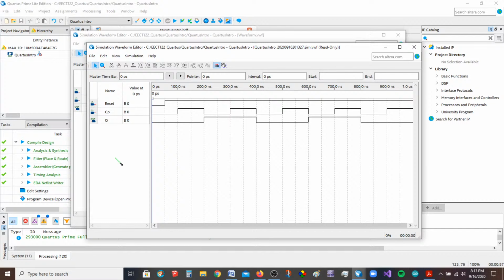So you can see, and this validates what I said about the frequency. This frequency has a period of 200 nanoseconds. This one has a frequency that's half that, right? The period is twice as long to complete one cycle. You can get 2 cycles in the amount of time you can get 1 cycle of Q. So that's why we say that the output Q is half the frequency of whatever the clock pulse frequency is. Or the other way to say that is the output period is twice that of the clock pulse. Okay, so either way you say that, it's valid.